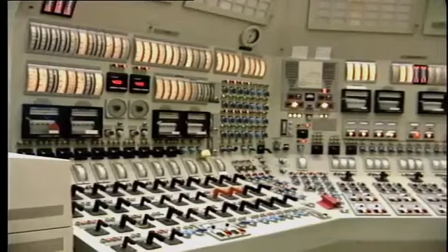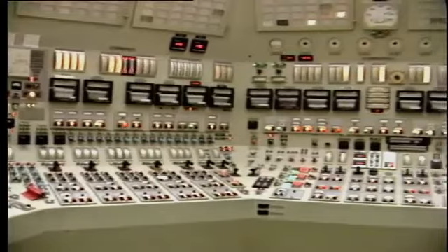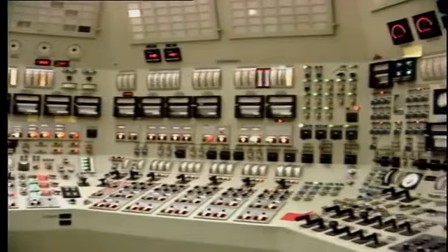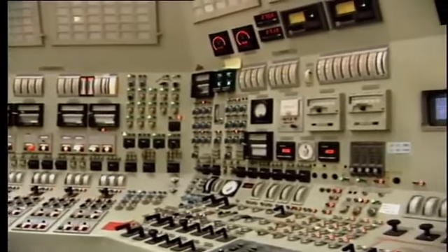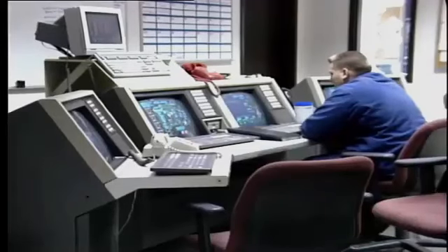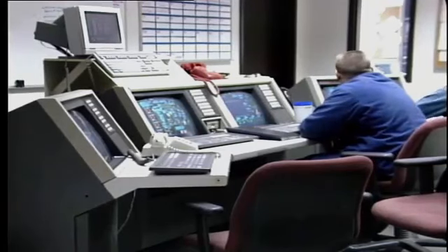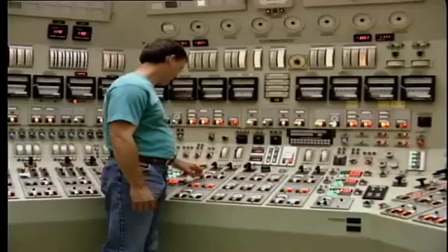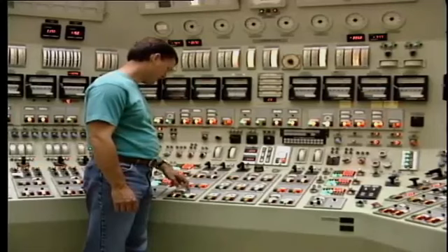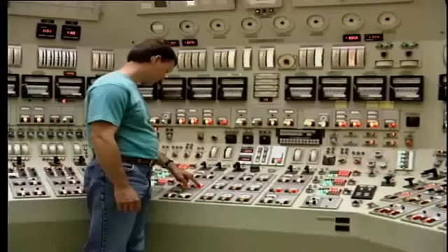But first, let's take a look at the control devices that permit the operator to run the boiler as efficiently as possible while responding to changes in load demand. We have already studied monitoring equipment, both the traditional control panel and the modern operator's console. In either case, the operator is able to stop and start equipment and make adjustments remotely, that is, from his central operating position. The operator can also manually adjust all of the major operating parameters, such as fuel input, combustion air, feed water flow, steam temperature, and so on.